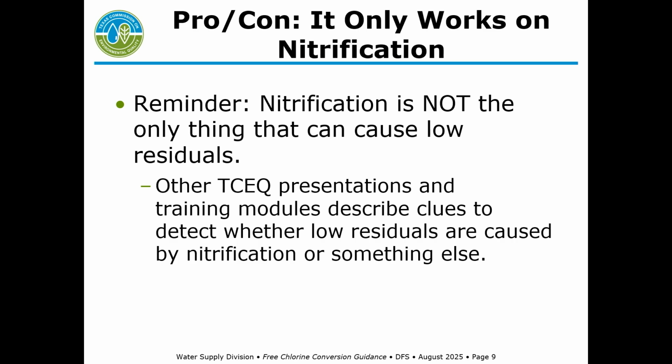The free chlorine conversion only works on nitrification. Nitrification isn't the only thing that can cause low residuals, and we have other presentations and training to help you detect if this is a problem from treatment failure, maybe increased demand in your raw water source, you have cross connections or unstable chloramines. If you have any of those issues, a free chlorine conversion is not the solution.